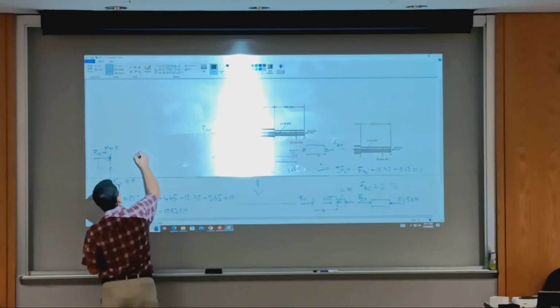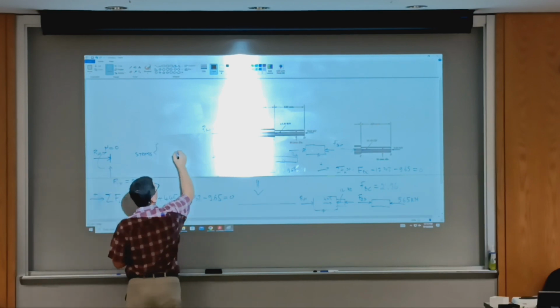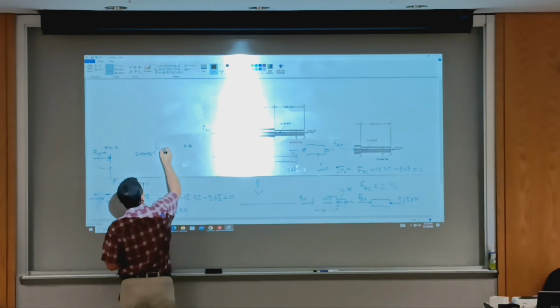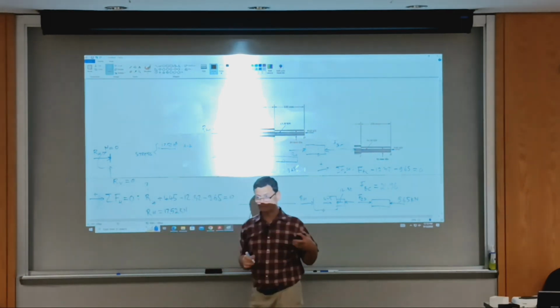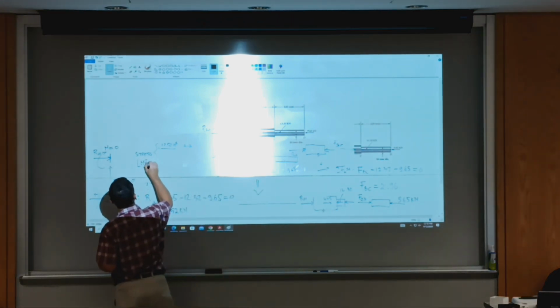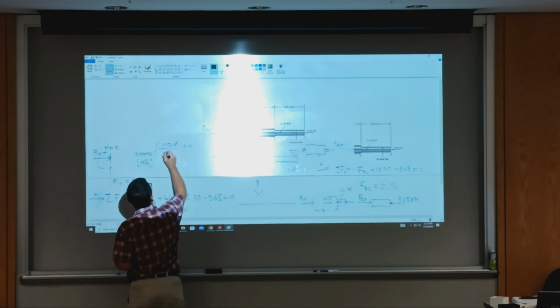So between A and B, we have stress negative 17.52 times 10 to the power 3 to go to newtons. And area should be in millimeters to get megapascals, remember? So stress would be in megapascals. So it'll be pi times 25 squared over 4.